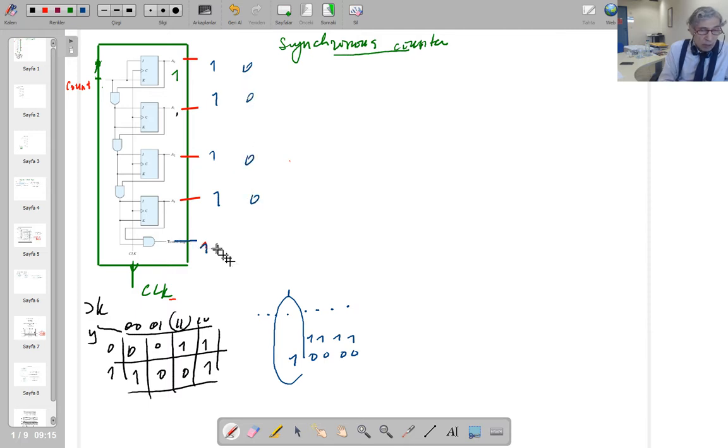The next 4-bit counter's clock input is going to be this input. This clock input affects this new integrated circuit. That means that 4-bit signal is going to be increased by 1 when the 4 least significant bits are full, there's going to be 1 clock pulse here.